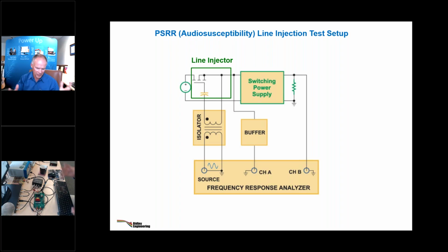By the way, you enterprising engineers, this is a nice way to upgrade your stereo for free. You tell your manager you need to measure output impedance well, and you go to the stereo store and buy a nice audio amplifier, and they have pretty wide bandwidth. They'll put out about 40 volts and 20 amps, and then you can drive the hell out of your kilowatt power supplies. And when it's done, it just kind of needs to go home with you at night. You're working from home anyway now. But yeah, I've done that several times. I bought power amplifiers from audio companies just to add more oomph to the test method.